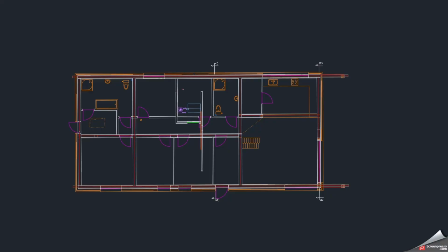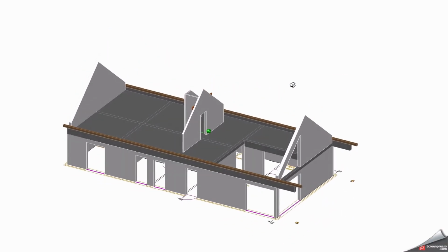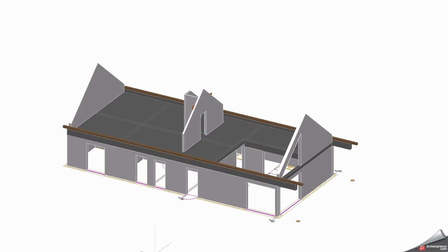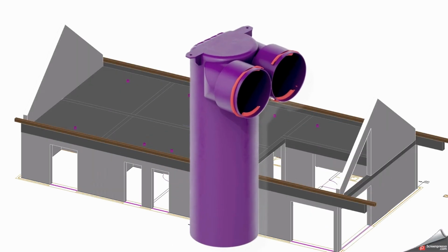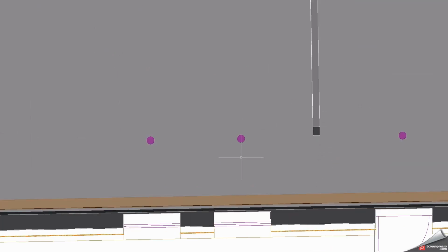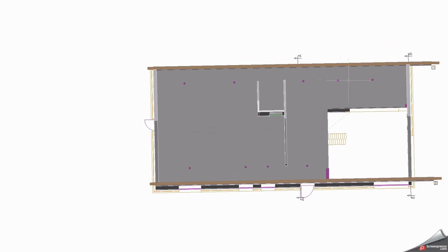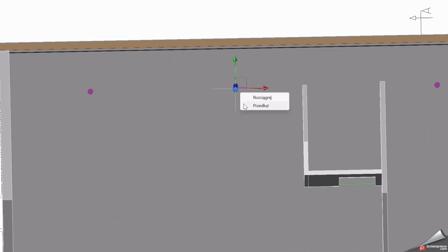In order to plan the routes for the ducts and the arrangement of the individual installation components, I prepared a simplified 3D model of the building. The expansion boxes within the clean rooms were strategically placed in alignment with the window axis, roughly 1 meter from the interior edge of the wall. Conversely, in the dirty room areas, the air diffusers are situated approximately in the central part of the room, but they also maintain a distance of 1 meter from the wall.